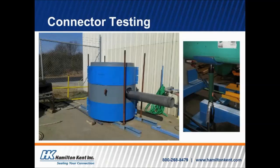And as I mentioned a minute ago, this is some testing. This is a manhole that we have at our plant where we do testing for our own boots. You can see that we have an elaborate structure set up here, with bands that go around it to offer more structural strength to the manhole, because we're pressurizing the manhole to 13 psi, which may not sound like a lot, but that's a lot of pressure that manholes are not typically designed to withstand. Unless you ask for that, that's not the way they're going to be designed.